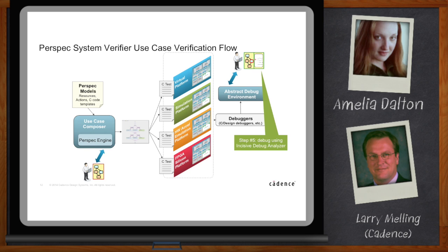And then the last piece of that puzzle is really the coverage level analysis. So you get all those coverage statistics, and then you can not only go in and do analysis on what's left that's open that I still need to cover, but also consolidate that system level coverage with all the old IP level coverage and things that have already been done. And now you give a complete report to your management of how well this has been tested and what's been covered.